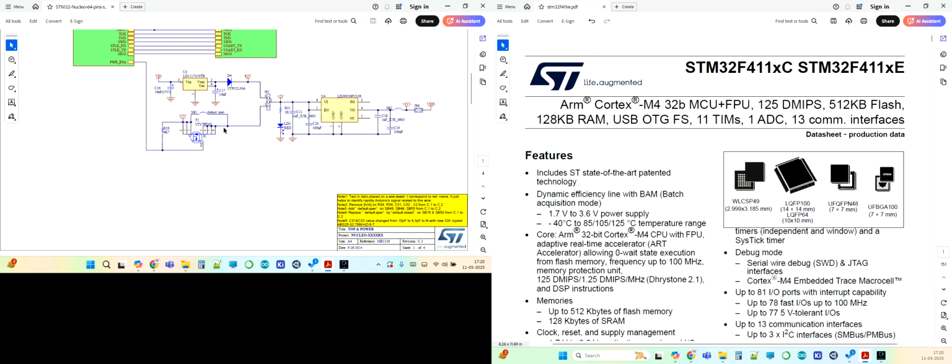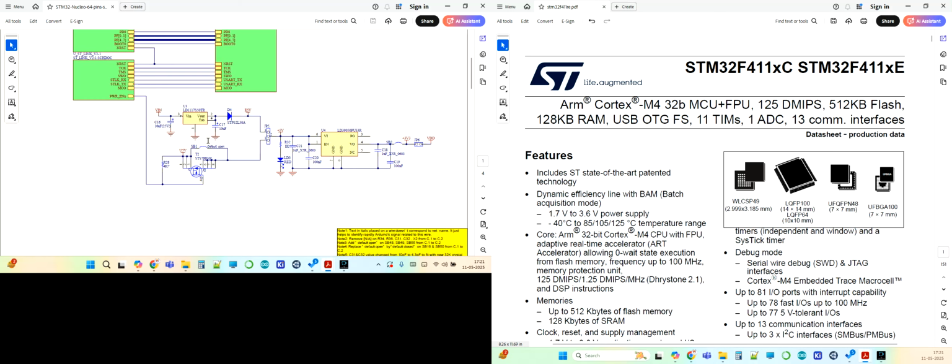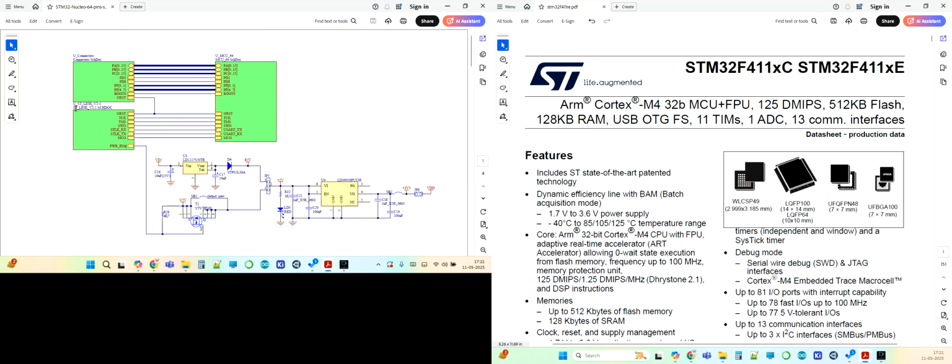Now you know that the main controller is getting powered separately, the ST-Link is getting powered separately. To avoid any power issues or power sequencing issues, what they have done is they have something called power enable, which is actually controlling the gate of this particular MOSFET, such that only when the power enable signal comes, the U5V will be passed to this particular LDO. So that means in our circuit, we have to understand that first ST-Link power should be up, and then comes the main controller, which is the correct sequence of powering the board. So this is how the board powers up.